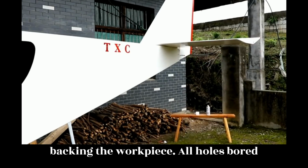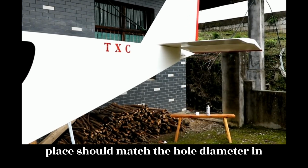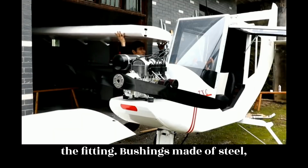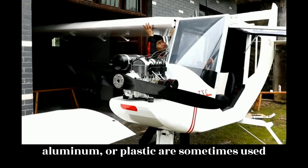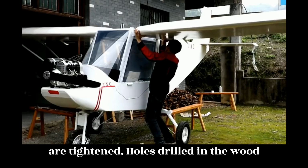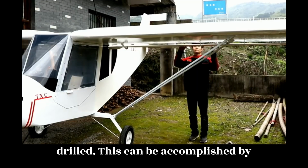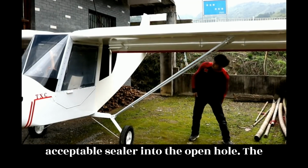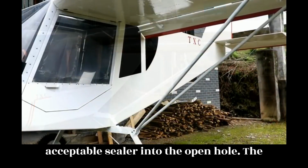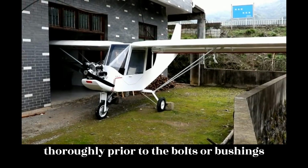the workpiece. All holes bored for bolts that are to hold fittings in place should match the hole diameter in the fitting. Bushings made of steel, aluminum, or plastic are sometimes used to prevent crushing the wood when bolts are tightened. Holes drilled in the wood structure should be sealed after being drilled. This can be accomplished by application of varnish or other acceptable sealer into the open hole. The sealer must be allowed to dry or cure thoroughly prior to the bolts or bushings being installed.